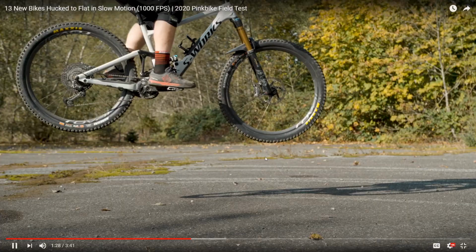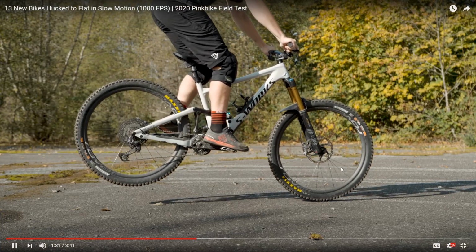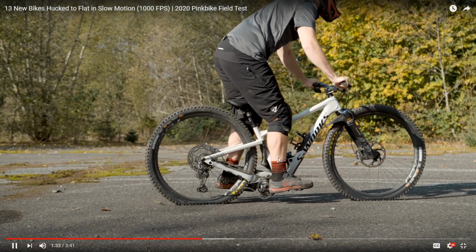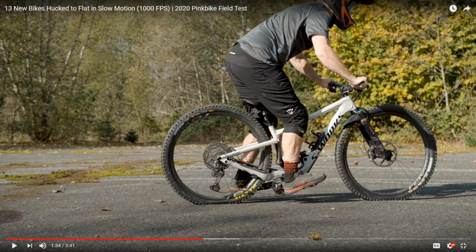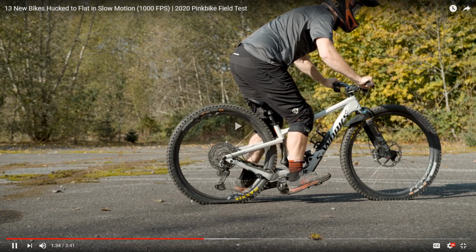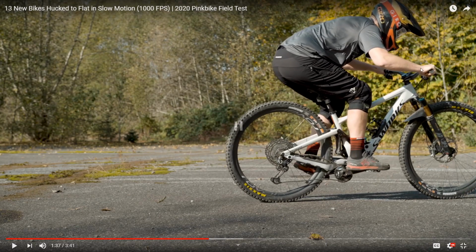And over a short period of time, right, the load goes through the forks and gets absorbed by the suspension. At this point, the suspension isn't doing anything anymore, and all of the load of accelerating the rider upwards, or should I say decelerating him from falling downwards, is now going through the frame, right, for a short period of time. I would argue that the handlebars aren't really seeing that much force, but it's mostly in the pedals. But I'm going to put, let's say, half of his weight on the handlebars here. Okay, and it's going to be somewhat forward and somewhat downward.